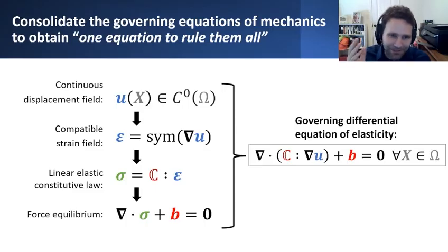And so we restrict our attention now to functions that are continuous functions defined over whatever particular domain we're looking at, and hence we'll use our conventional notation to refer to the displacement field as belonging to the set of all possible continuous functions. From that, we could take that continuous function and plug it into our strain displacement relation. We could plug that into the equation for the stress tensor, depending on the strain, which in turn depends on displacement.